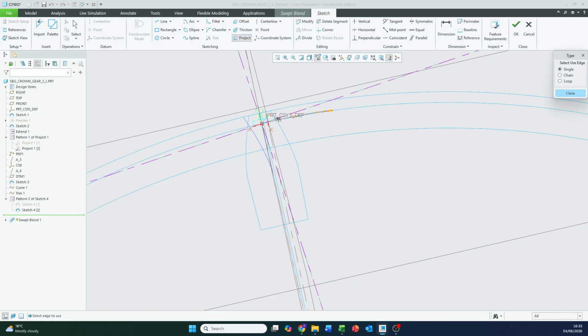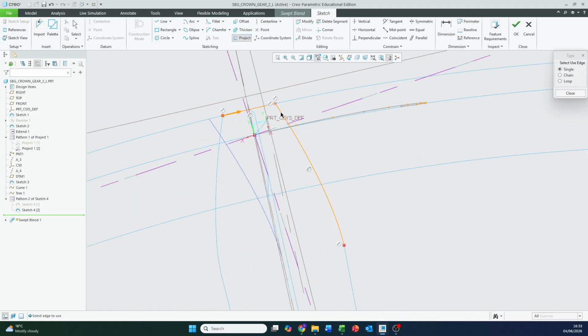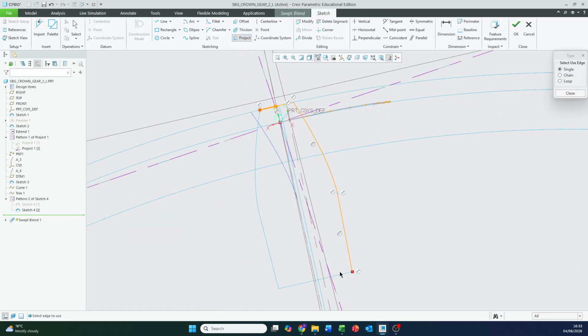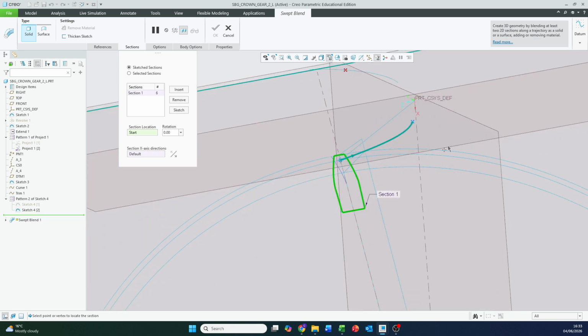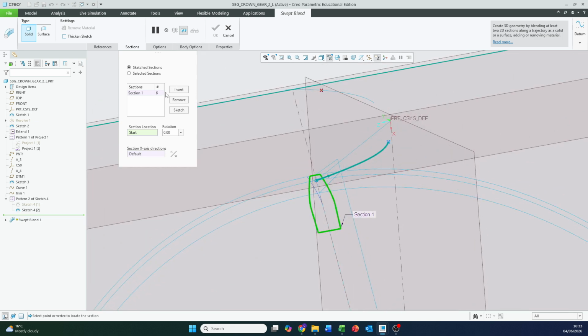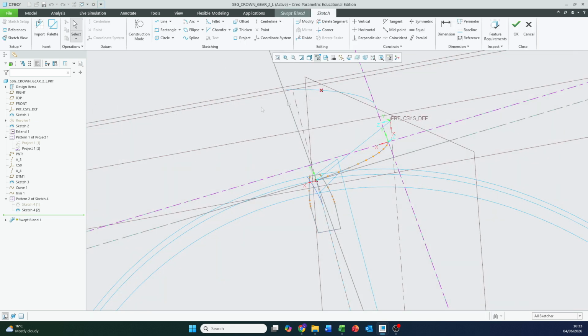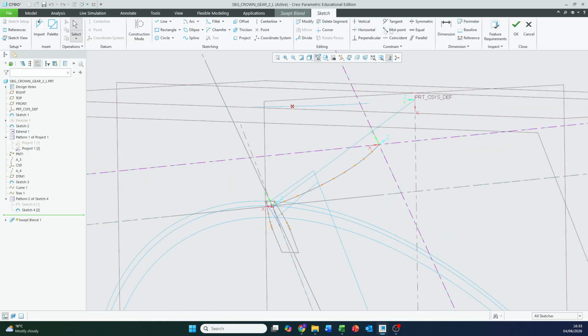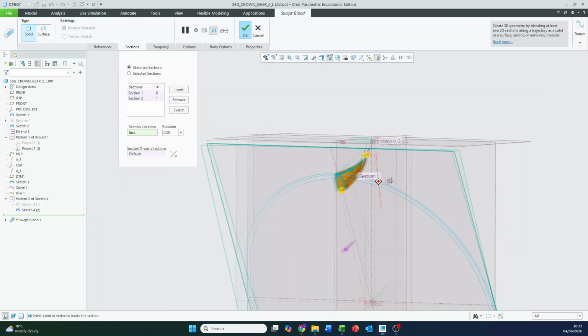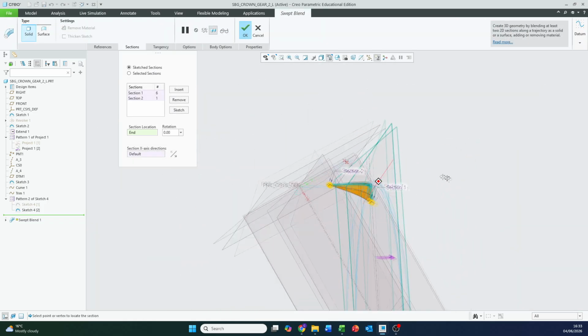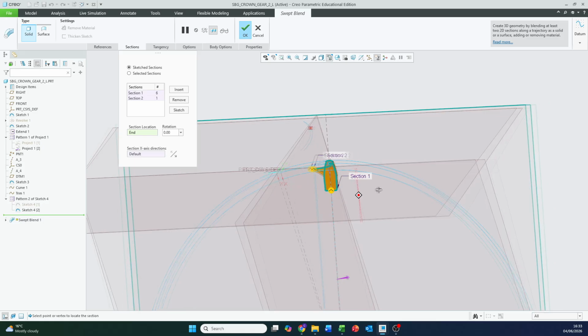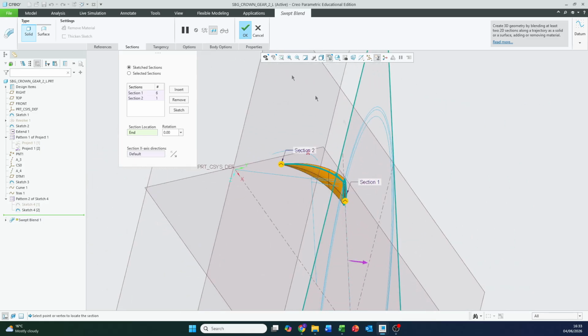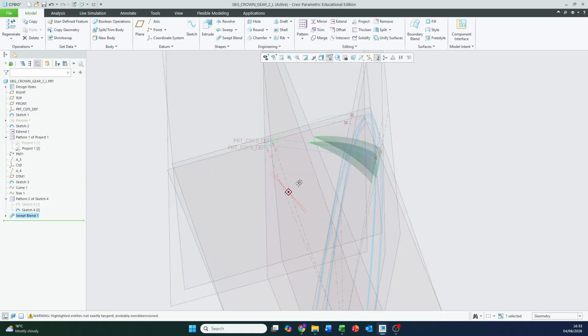And let's project this profile into existence. Okay. Next, we are going to insert, sketch, and then we're going to put a point again at the end here and press OK. And there is our cone gear tooth geometry coming into existence.